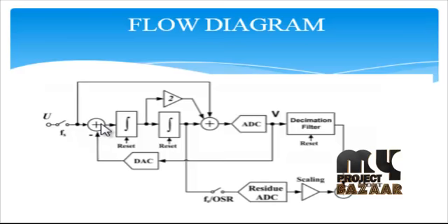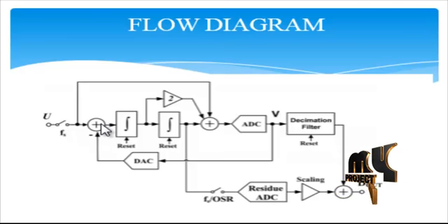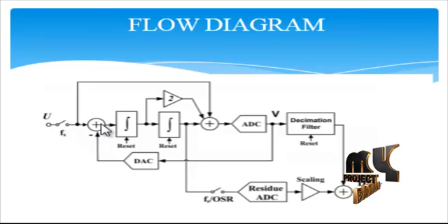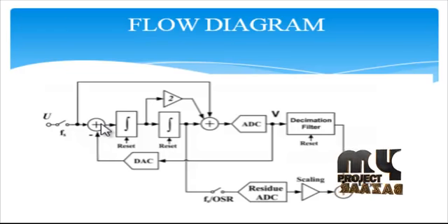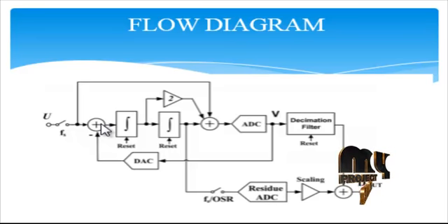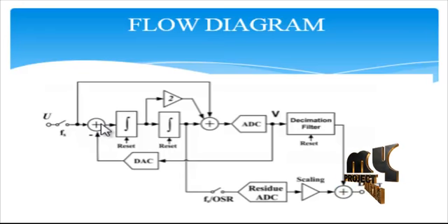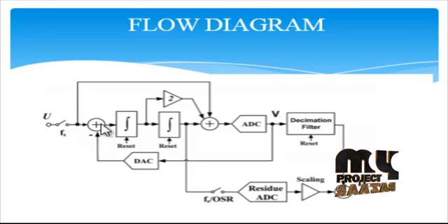Then this overall structure looks like a SAR based ADC functionality, but we use the two-step incremental logic for the sigma delta functions in the ADC function. This ADC function feeds back logic to the DAC operation. This DAC operation is the feedback comparison based process. The comparison process proposes the decimation filter, these filtering components reducing the unwanted data leakage and data losses for the overall A to D conversion process, and the residue voltage maintains the output voltage level